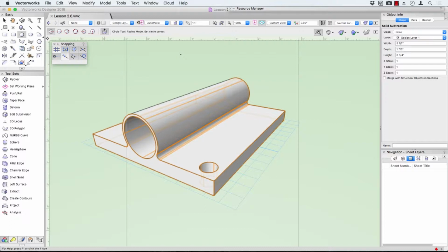So let's try that again. Find that edge there, hit the T key, and find this edge and hit the T key again. Now it didn't work. Did it work straight away? No, I can't see the offset, so let's do it again. There's my offset. Offset and offset. So click, and this was 0.25 of an inch. Enter once, enter again, and that creates my circle. So I can grab hold of that circle, click, come all the way through, hold down the Option or the Alt key, click again.